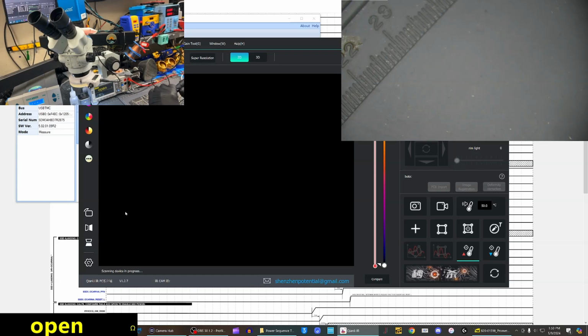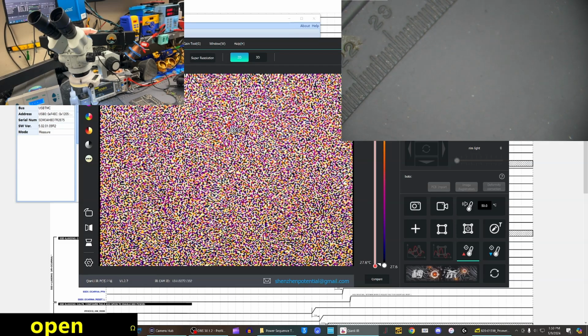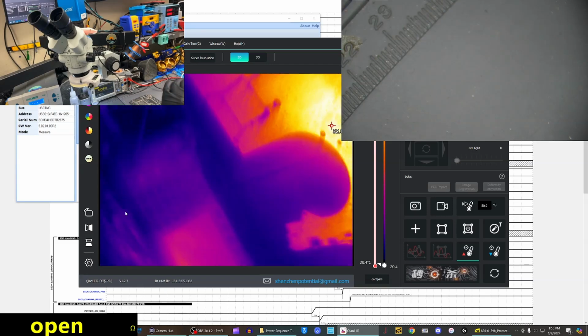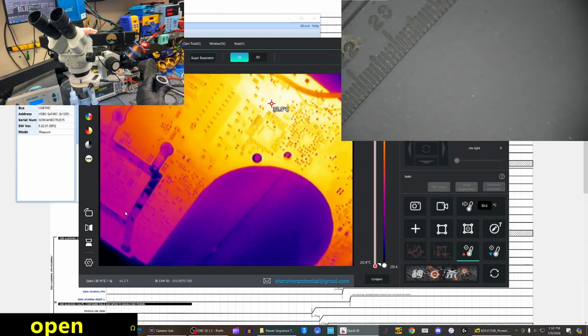In any case, what we basically want to see is, when we connect, that immediately it's drawing like 3 amps. If we didn't see this climb up, then this line probably doesn't actually have a short. If we just soldered 2 wires to ground, we wouldn't really see the current climb up like this. You should see current climb up on there.